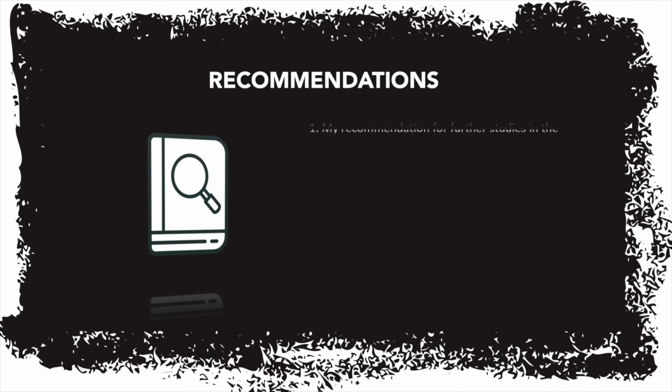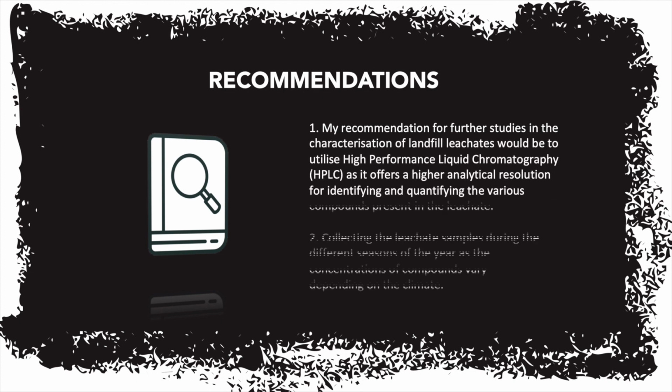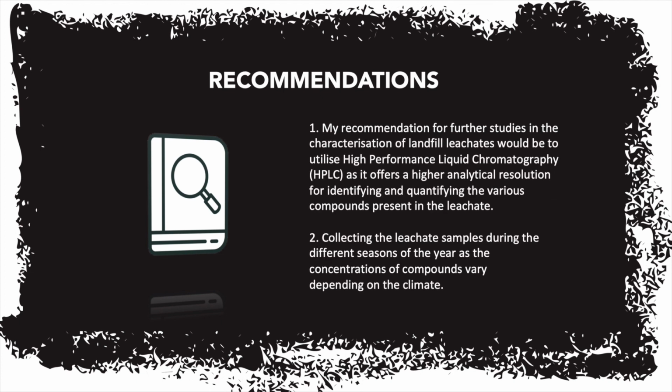My recommendation for future studies would be to utilize high-performance liquid chromatography, as it offers higher analytical resolution for identifying and quantifying the various compounds present in the leachate. And secondly would be collecting the leachate samples during different seasons of the year, as concentrations of compounds vary depending on the climate.